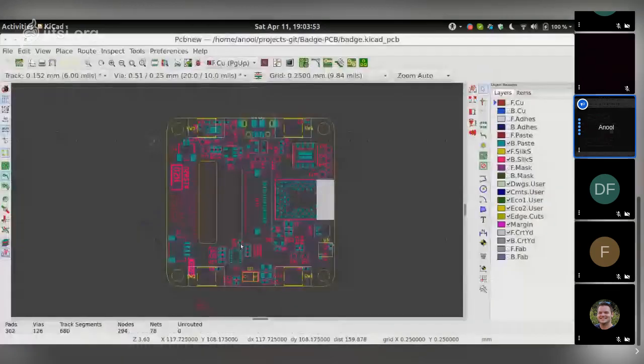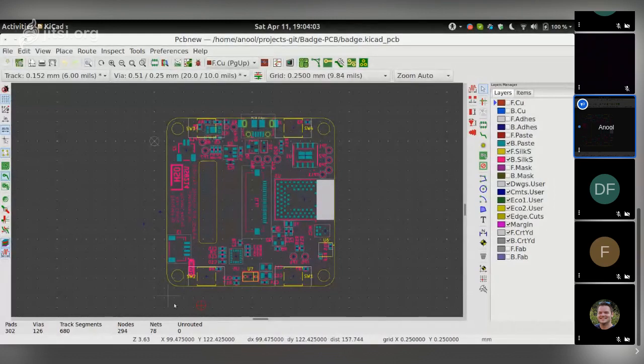So that's what I thought. Let me see how we can design footprints that retain information such as the center of the circles or the center of the arcs, even if you draw it in a CAD program like FreeCAD and then bring it into KiCad. So if you've drawn a circle in FreeCAD, it needs to be imported into KiCad as a circle too. That helps. And in order to do that, let me start off with a simpler project. I'll come back to this later to see how we can change this whole thing to a more reasonable outline.